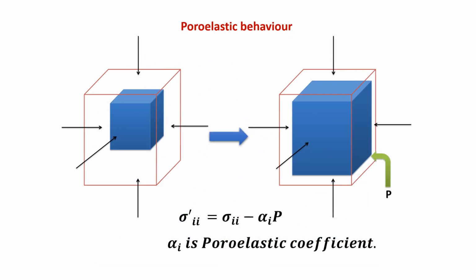As part of the triaxial process, SIGRA can also measure poroelastic behaviour so that the effective stress in rock may be determined. This is achieved through gas injection into the core specimen that is being triaxially loaded. Poroelasticity describes how fluid pressure causes the rock mass to deform. To the left of the above figure, the red wireline cube is deformed by a unit stress to the blue cube. To the right, it shows the same cube that has had fluid injected at a unit pressure. The cube partially recovers its dimension. The poroelastic coefficient is a measure of the fraction of recovery.